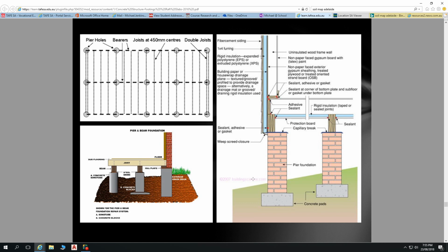And if you have one that's not, well then that gets taken up at the end here, and then you get some wastage of your floor sheeting. But you have to have these joists lining up under where you have joints. Also, at this end, you do double joists. Wherever your joists end, you do double joists there, because you're going to have load-bearing walls on top of that, and you also want to have some.